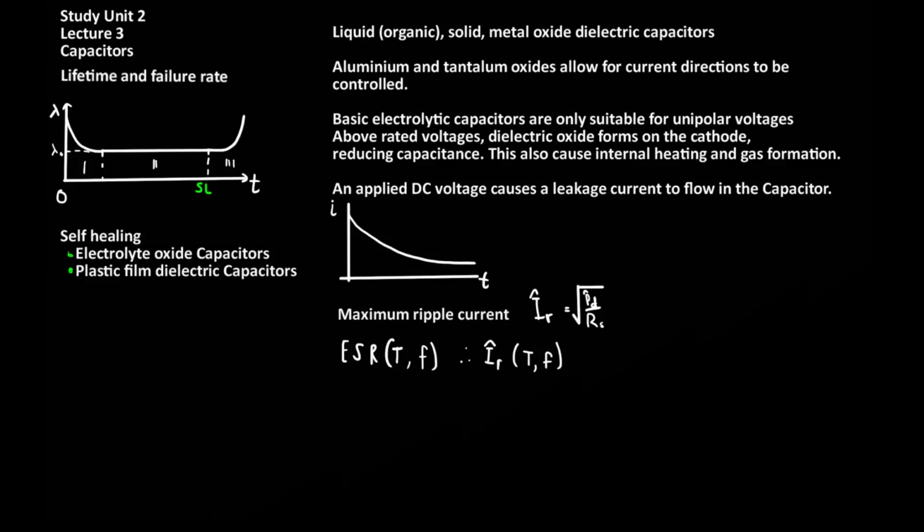In metallized plastic film capacitors, the high field strengths effectively destroy the defective area, and this region will no longer manifest with a very high electric field, thus protecting the rest of the device from the overvoltage failure.